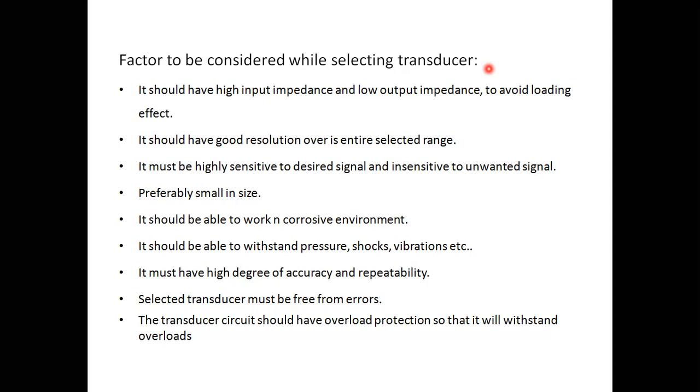Because if the sensitivity is too high, then we have to compromise on stability, since stability will be decreased. And if the instrument is less sensitive, then I will get errors in the output.